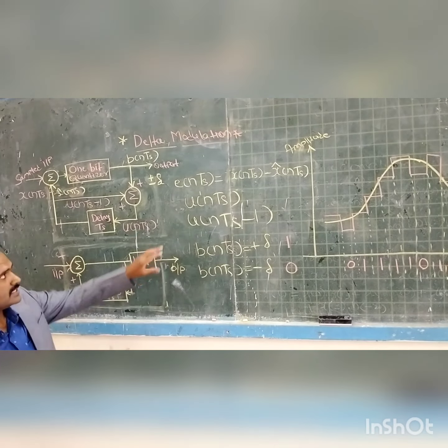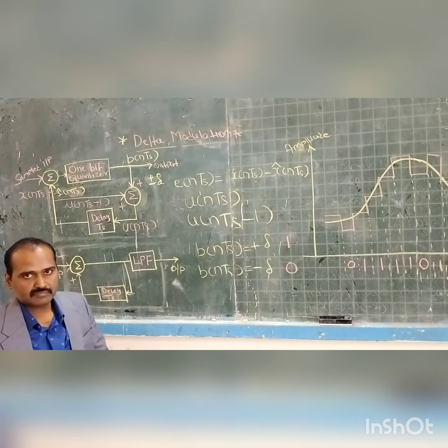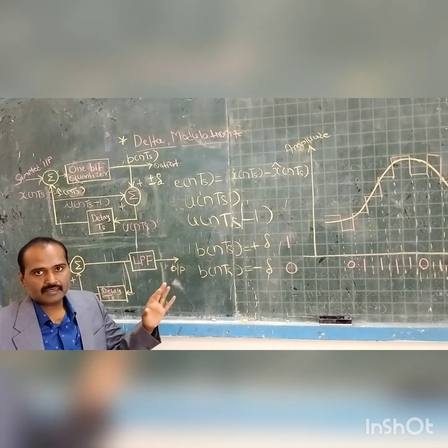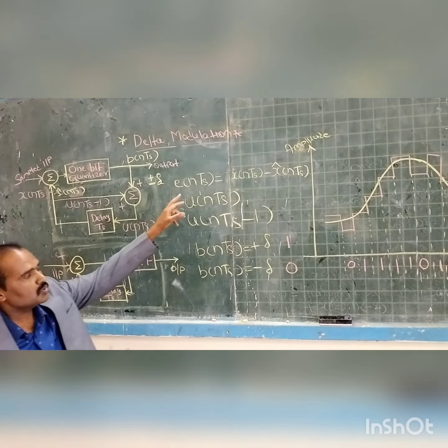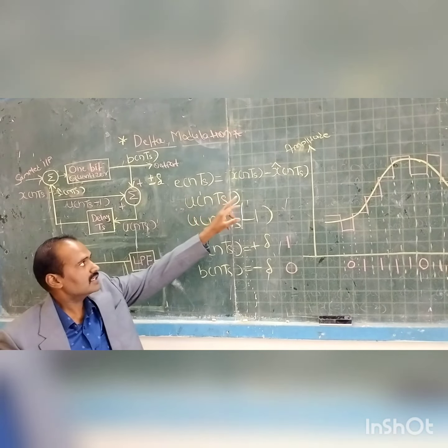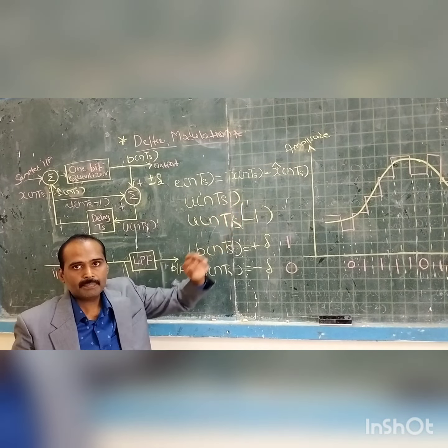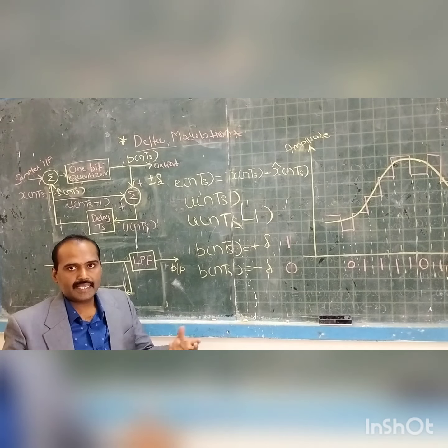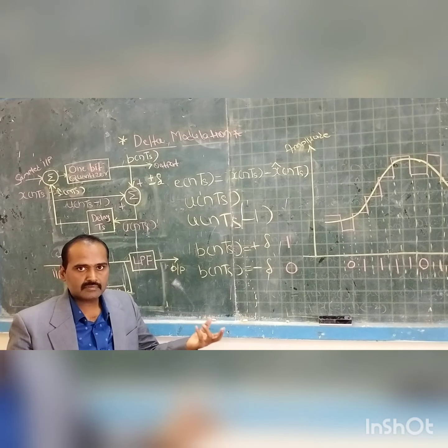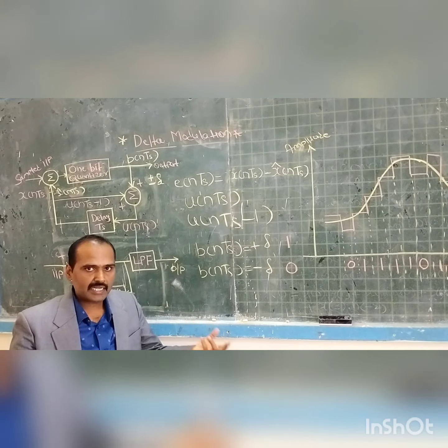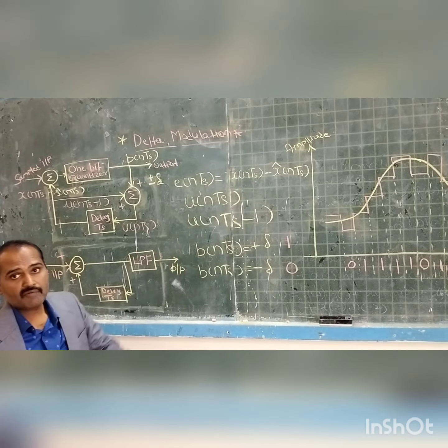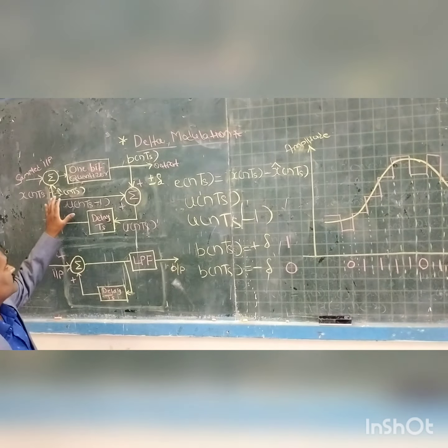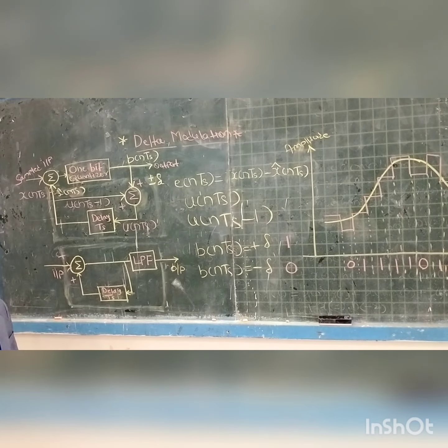First, e stands for the error, the error present at that particular sample. How are those error signals generated? It is the difference between x of nTs and x cap of nTs, where x of nTs is the present sample value, the discrete time signal as compared to the continuous time signal. Now the question arises, how is this x cap of nTs generated?